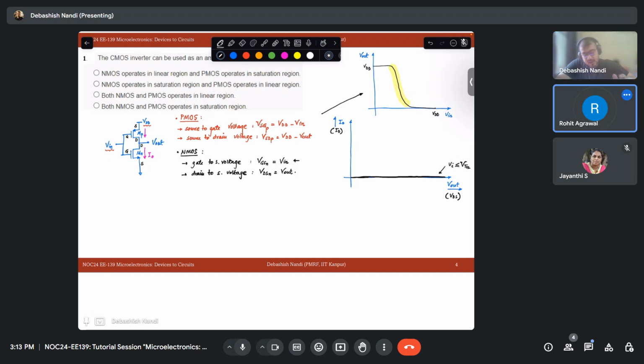Now, what is the case of NMOS? What is the case for PMOS? For PMOS, when my Vin is 0, what is my VSG? It is VDD. So that means PMOS is turned on.